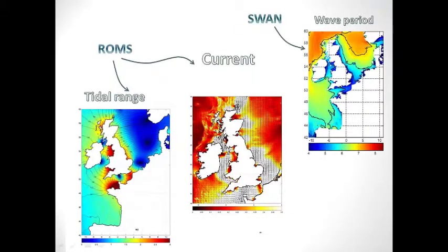We developed a 3D tidal model of this region and a decoupled SWAN model of the region. So using the graphs that I showed, we have a vertical tide and horizontal tide at each single point over the European shelf seas, and then we can compute the effects on the power. So this is the vertical tide, horizontal tide, tidal ellipses, and the wave power. It's based on SWAN and ROMS, the regional ocean model.